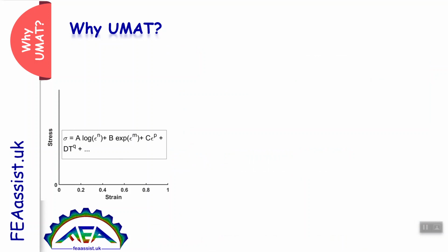So what can you do? Then you need a place to write this equation, or your equations, and tell Abaqus to obey this behavior to solve my problem. This is the reason we need UMAT, because our equation is new.